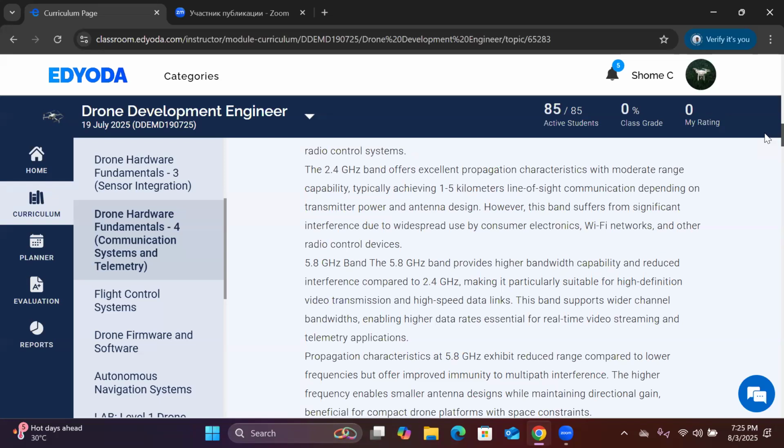Now I want to increase the range to 50 kilometer. So I have to increase the range 10 times. So in my RF transmitter chain, the RF power also we need to increase 10 times. It is not logically correct, but you can say approximately 10 times because these are logarithmic increments. It is not an arithmetical linear increment. So if I increase the RF power by 10 times, automatically my range will be increased by 10 times, from 5 kilometer to 50 kilometer. That is not true. But for the sake of the example, I am citing this. So if my power is 30 dBm or 1 watt, I need to increase my range.